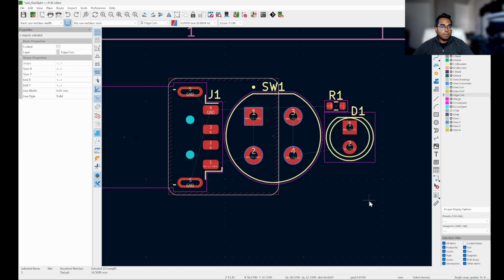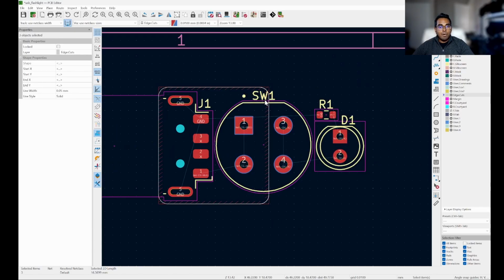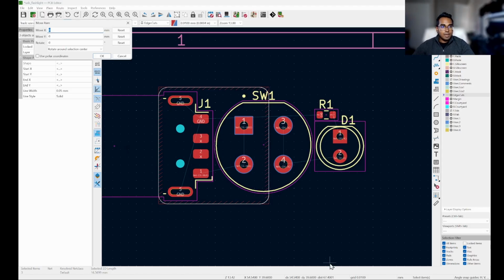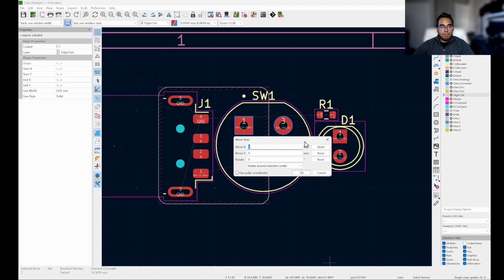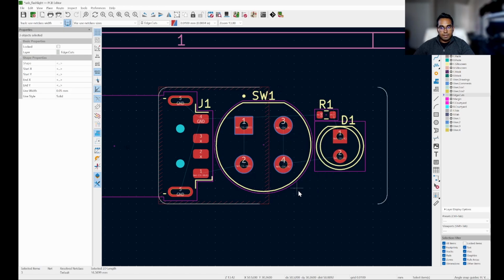let's say 14 millimeters. So what I can do to keep them all exactly in the same y coordinates, the same vertical coordinates that they are right now, but shift them over horizontally, is I can press the Shift M shortcut. And this gives me a Move Item menu. I can type in the 15 millimeters that I want to move my outline by in the X field, and then press OK, and it will have shifted over. Just like that. That's perfectly in the same y coordinate as it was before. It's just horizontally moved down.